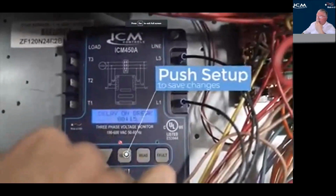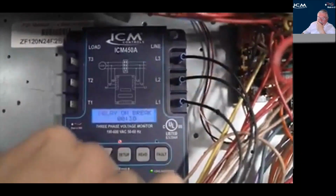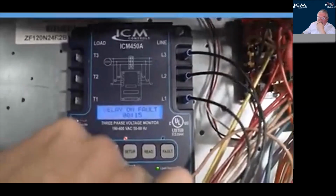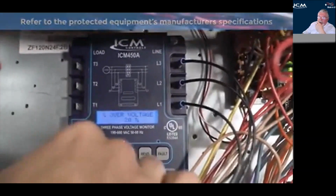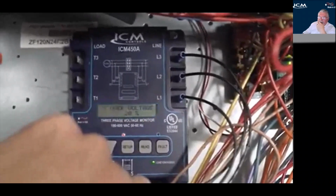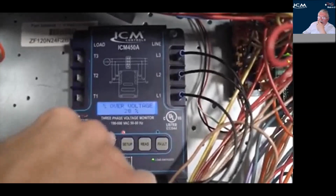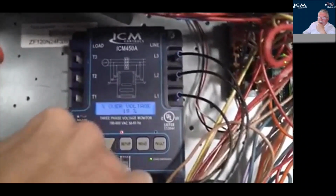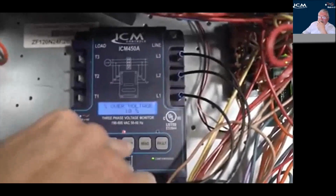Delay on break is just your timer, how long it locks out. Leave that at 15 seconds. Delay on fault, 15 seconds. Next is your over voltage. This is where, just the same as the previous model, this is fully programmable and customizable. We're just taking this one down to 10% just to show you how programmable it is.